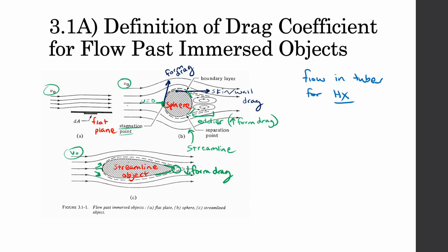For these types of problems, we might want to predict the frictional loss and force on the submerged object. And then we have this layer right here, which is basically the boundary layer, where inside this is going to have a laminar smooth flow. And then we can basically use that. At the edges of this, if we go outwards from this, we can assume that we'll just have the bulk fluid velocity of V naught. We also understand that the tangential stress on the body due to the velocity gradient in the boundary layer we refer to as the skin friction.